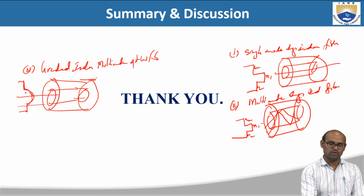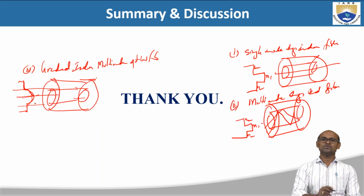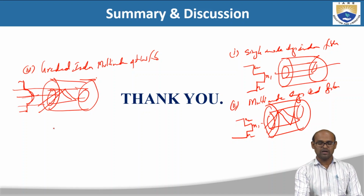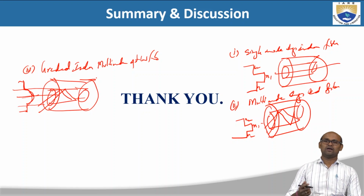So this is the core cladding boundary. It is maximum along the axis of the fiber, and it decreases to match the refractive index of the cladding at the core cladding boundary. So this is the structure of the multi-mode graded index fiber. You can have higher order modes and lower order modes. It is very useful in applications because even though there can be lower order modes and higher order modes, the time for reaching the output end for the lower order modes and higher order modes is the same.